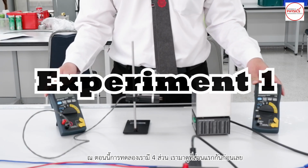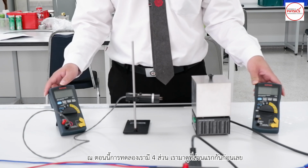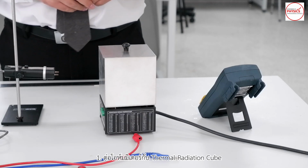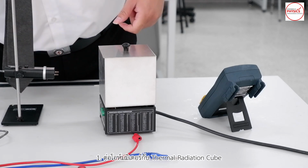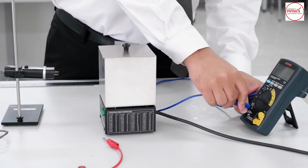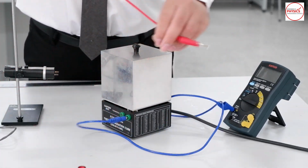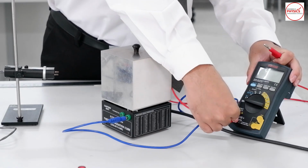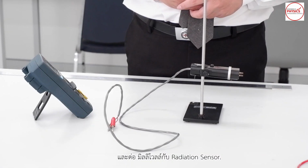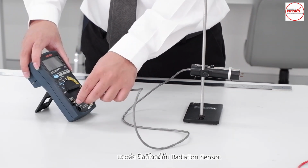Now, each experiment has 4 parts. Let's start with the first one, which is all about connecting the device. First, connect the ohmmeter to the thermal radiation cube. And connect the millivoltmeter to the radiation sensor.